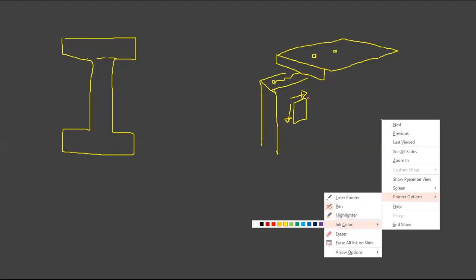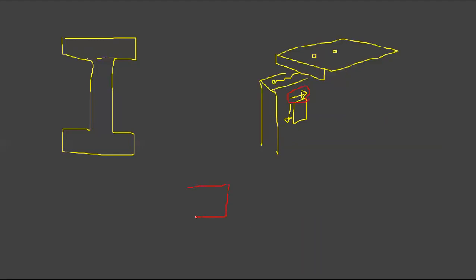Because if we take a small element, that element is in equilibrium with complementary shear stress. You remember, this couple is in equilibrium with this couple. That's how. So this is the reason most timber beams fail in horizontal shear, right?